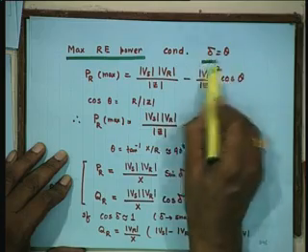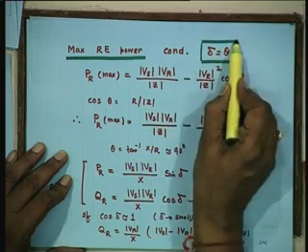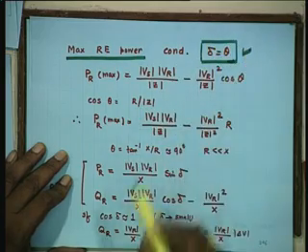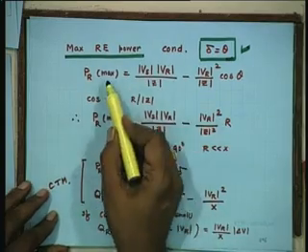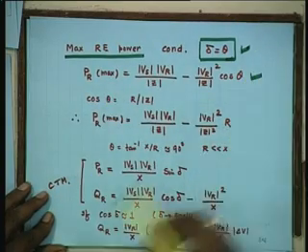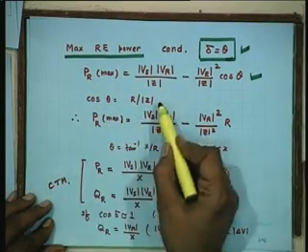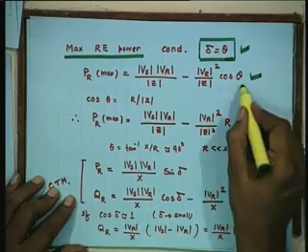As I was telling you, now the condition for maximum receiving end power is delta is equal to theta, and so PR max is this, where cosine theta is R by Z. This is the triangle.